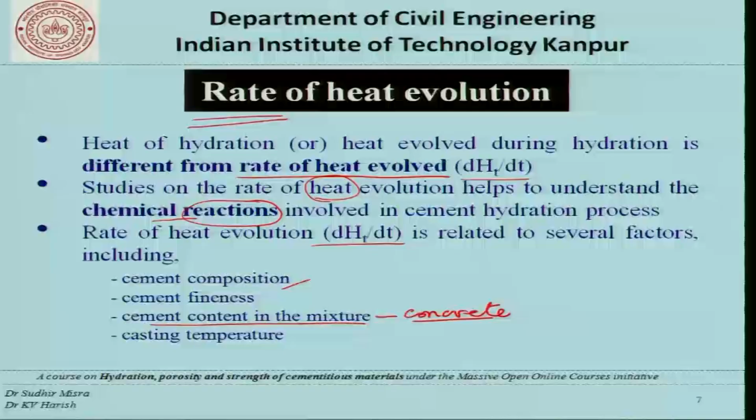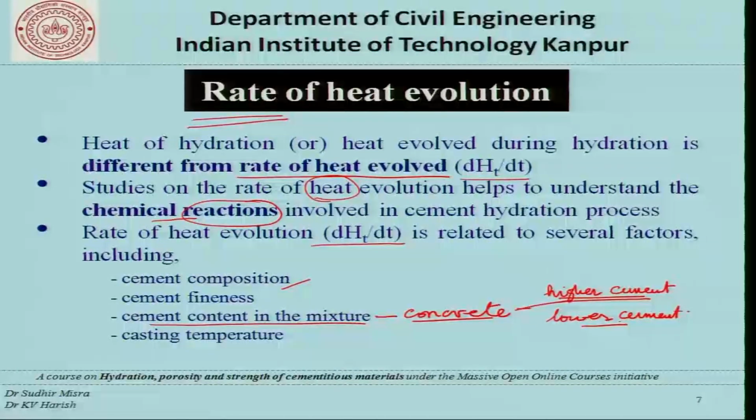Now, obviously, a concrete which has higher cement compared to a concrete which has lower cement, this concrete will have a higher heat evolution compared to this concrete.